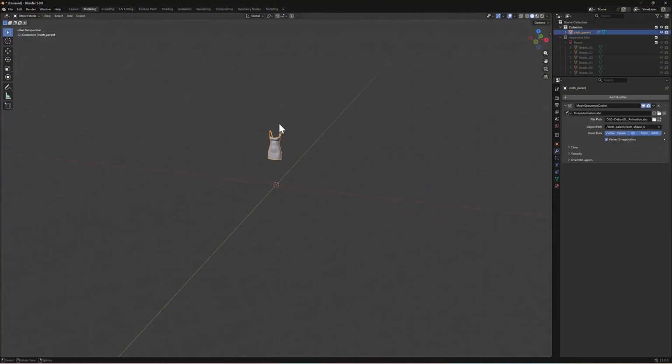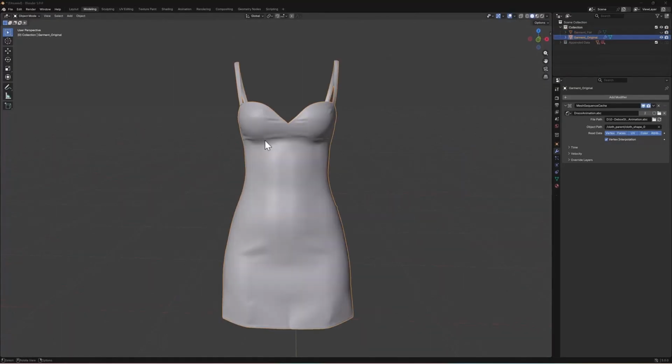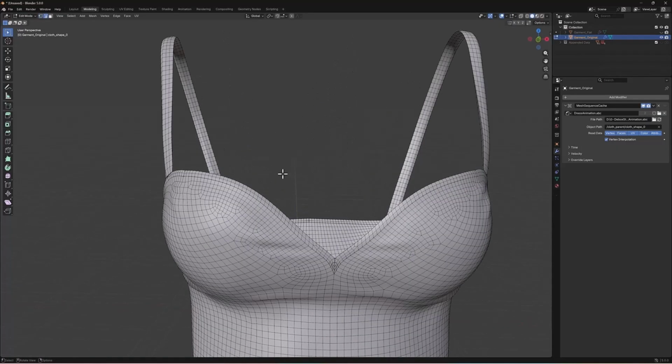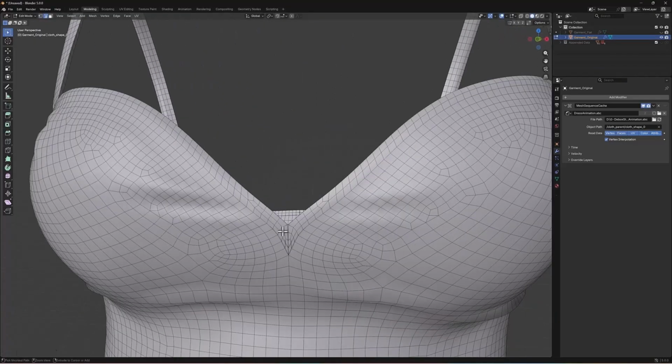But for most accurate and technical workflow, we need a flat version of this model that I will explain later. You can use the model's edges as curves. First, hit Tab and go to Edit mode. Press 2 to enable the edge mode. Now select the edges you want to use and duplicate them by pressing Shift D.